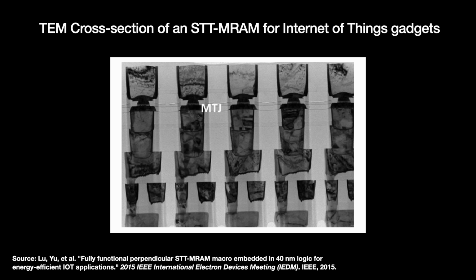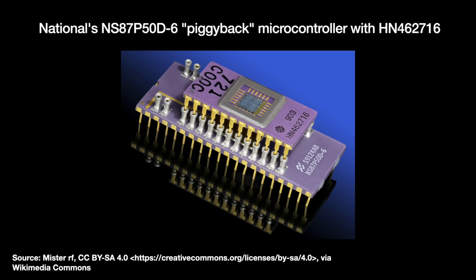Despite both TSMC and Samsung positioning STT-MRAM or ReRAM, eFlash remains quite resilient. Why? eFlash is a tried and true solution in a space where reliability matters more than raw performance. Most MCUs, microcontrollers, are still made using trailing edge nodes like 65 nanometers, though this is starting to change. And as we laid out throughout this video, the next generation contenders are not exactly free of trade-offs. The semiconductor industry is pretty conservative, and they're not apt to try new weird stuff until they have to.